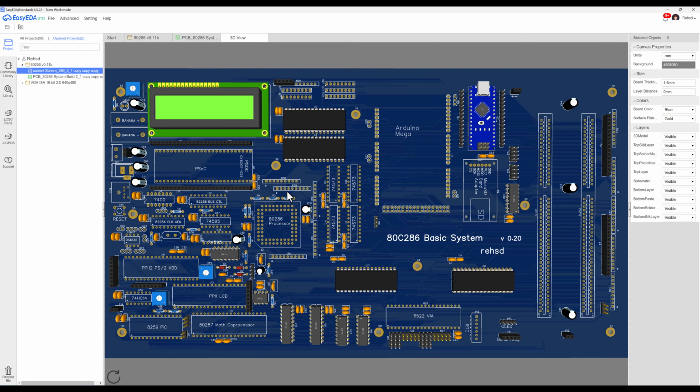I've also added internal bus pull-ups. So all along here I can basically pull up my values that are coming out for address and data. And I found that on a previous system, the breadboard system, that made a huge difference just on keeping those signals clean. So I put it in here optional. I can choose to use it or not use it, but I do have internal bus pull-ups. And to the right I still have my external bus pull-ups or pull-downs with a jumper. These I just set to all be pull-ups. I don't have a pull-down option.